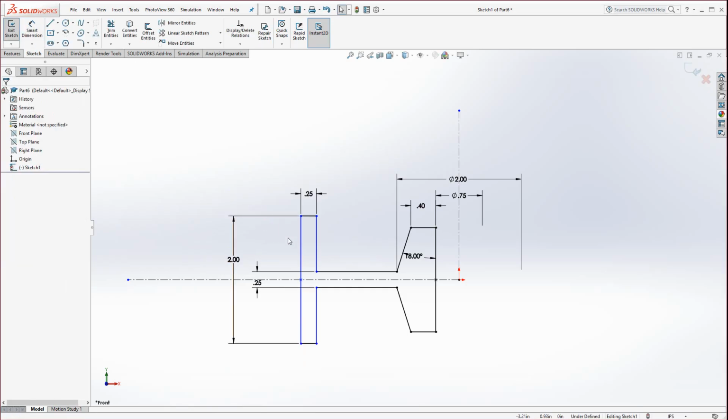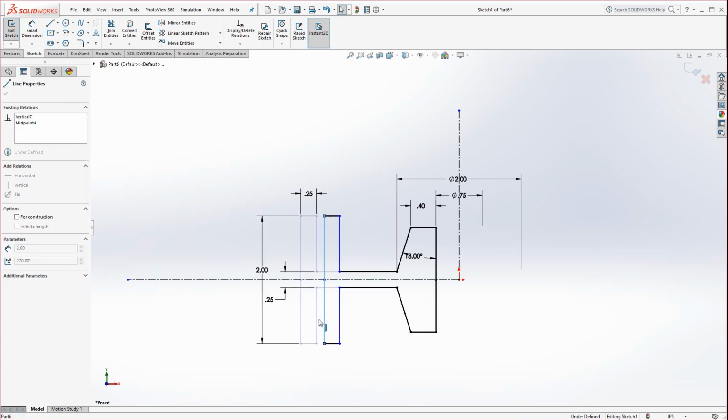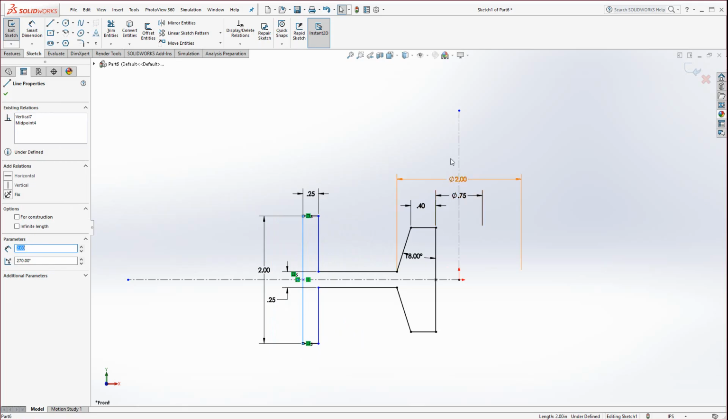And hit escape. Now you'll notice this geometry is blue. A number of students that I've taught over the years seem to not see this last dimension that's in the actual manual. Again, if you're not sure what is left over and you see it's blue, it means it's underdefined. As I always try and teach, try and make sure it's fully defined before you go into production. So you could just grab this after you hit escape, just drag it. And you can see it's missing the 5-inch dimension, which is the overall diameter of the wheel.